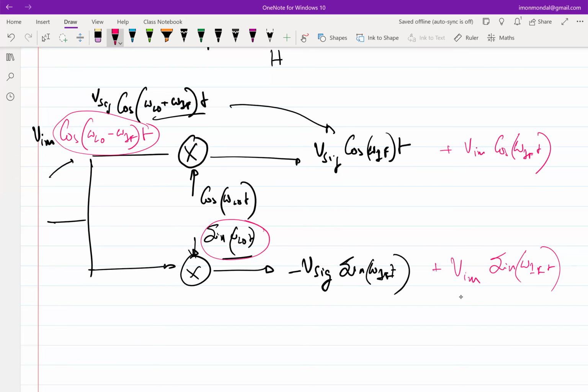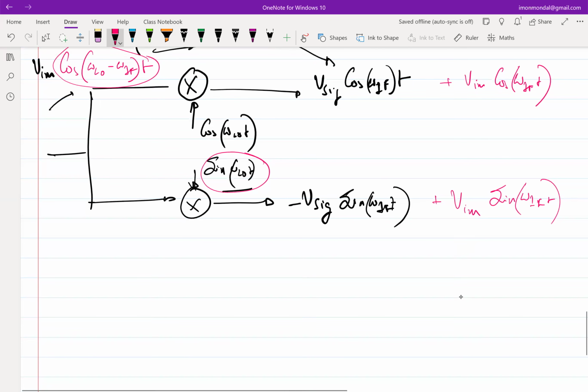I'm not showing it, just making a statement based on your experience of designing circuits; I presume you would agree that designing something at lower frequencies is comparatively easier than at higher frequencies. So at least the signal processing needs to be done at the lower frequency. So what I do is take this and do a 90-degree phase shift at IF.